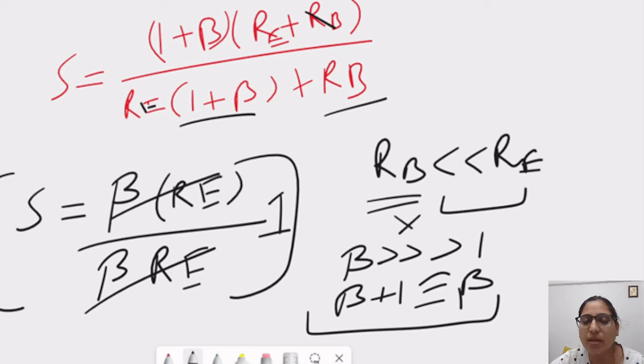So we can see that here the stability is 1. 1 is the maximum stability, or the best output of the transistor. From this derivation, it is proved that the stability of emitter bias is much higher than fixed bias. In last class, we considered overcoming the limitations of fixed bias, and in this class we completed the discussion on the stability factor of the emitter bias. We can clearly see that the stability of emitter bias is 1, which is very high in terms of transistor stability. So this is much for today. We will discuss another topic in our next class. Till then, thank you so much.